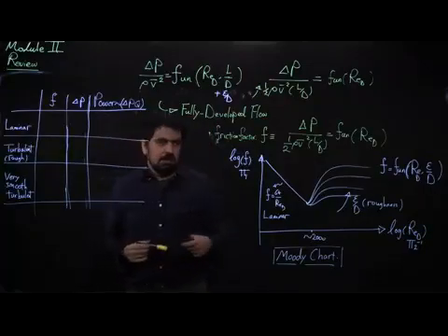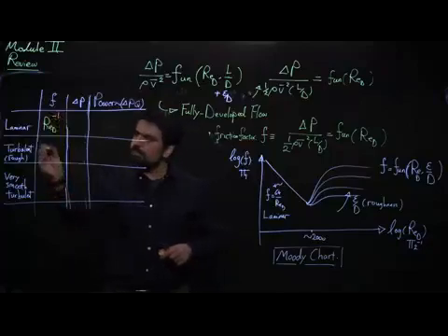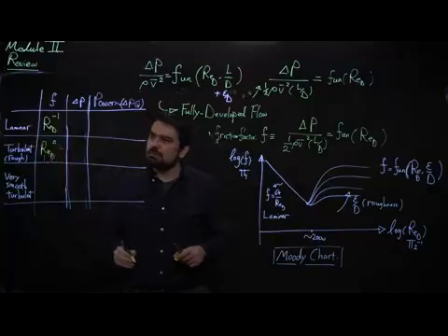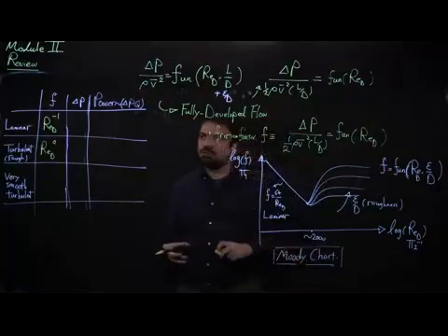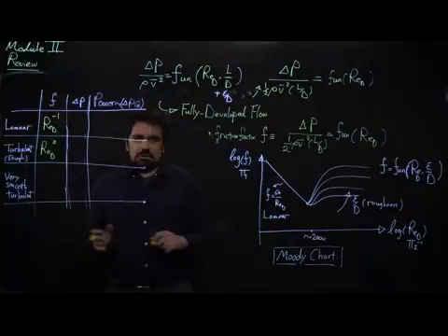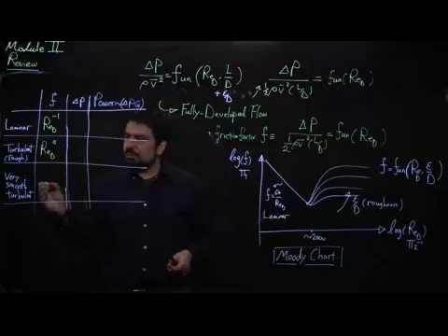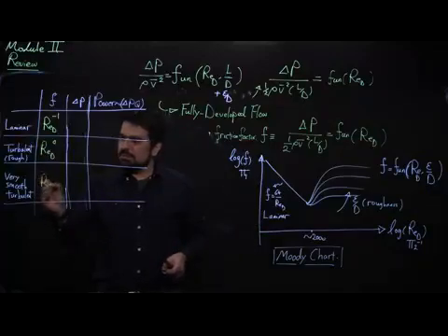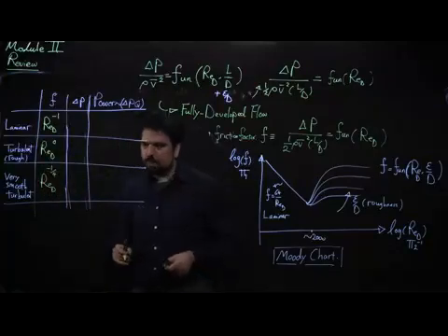In the laminar regime, we know that the friction factor goes as Reynolds number based on diameter to the power of -1. In the turbulent regime, we know that if the pipe has a certain roughness, it goes as Reynolds to the power of 0, which means that in the fully turbulent regime, finally, the friction factor becomes constant. In the very smooth turbulent regime, which means that the flow is turbulent but the pipe is extremely smooth, this doesn't go to a constant. It still decreases with Reynolds, but in a weaker manner than laminar. It decreases as Reynolds to the power of -1/4.